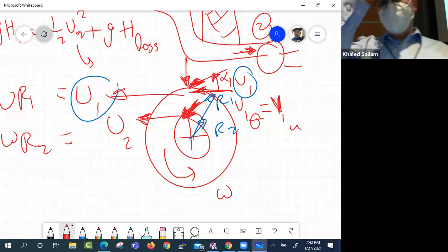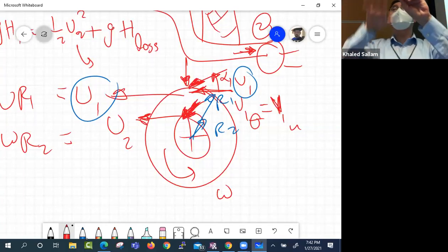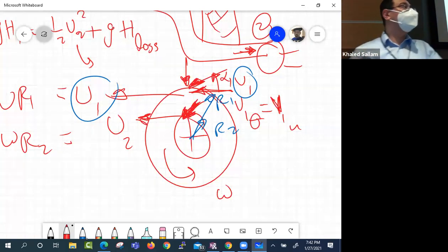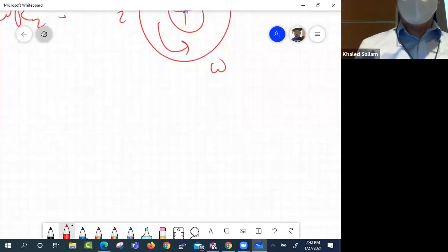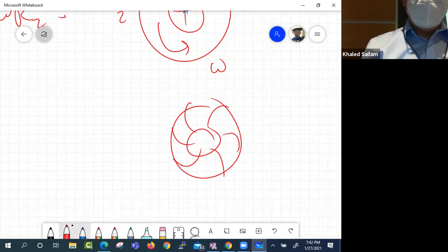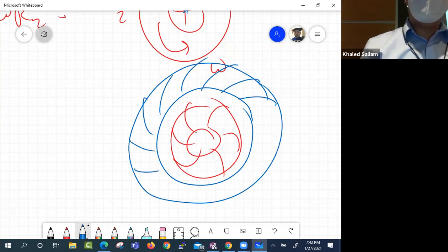So you will see he will come with a big V1 theta, a big tangential component. And how did he do this? Because of the stator, right? Because of this guy that has his plates like this, ready for the spinning. The rotor is preceded by a stator, plates that are not rotating.